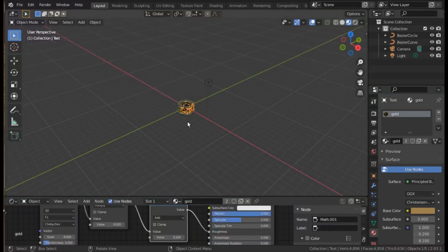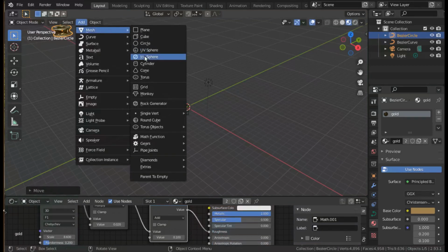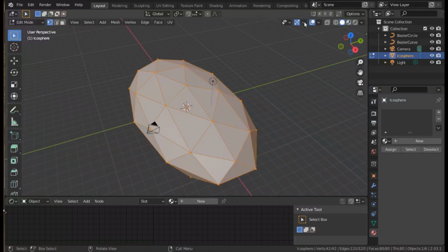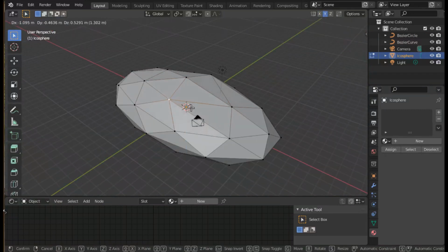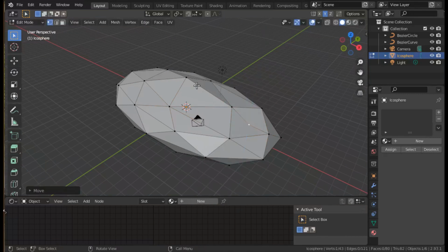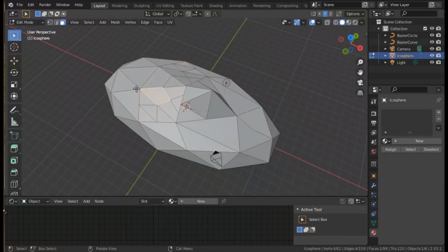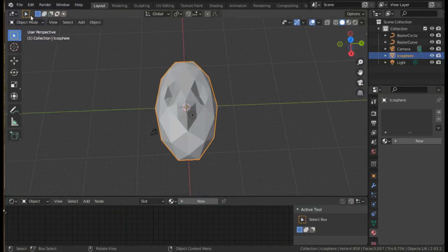Finally, move the ring up out of the way whilst we make the rest of it. Now we're going to add a mould, a former, which is just an icosphere, which we're going to alter into the shape of a mask, add a few vertices and displace them up and down. Notice I've set the Y symmetry because the icosphere doesn't have X symmetry.